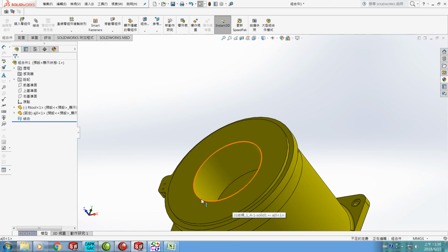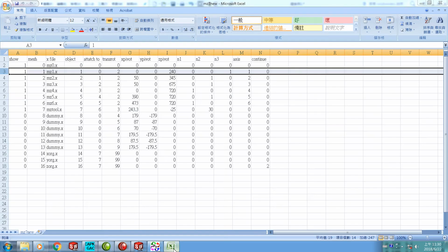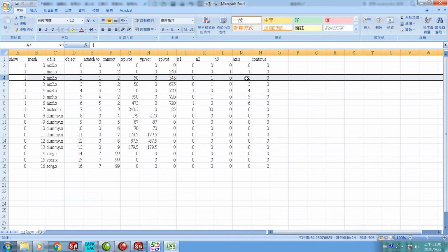We put a cursor on the edge of the circle, orange rough lines, rough circles shown on the screen. Then we simply press the left button of the mouse. The center will mark in here, the X0, the Y0, correct. Forget the Z value. So this 0, 0 verified.